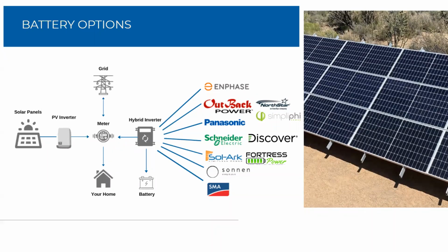So 4 kilowatt hours for a day means if I had a 12 kilowatt hour battery bank, that could get me easily through 3 days, 3 complete 24-hour periods. But if I have a 10 kilowatt hour day, my 10 kilowatt hour battery bank could potentially be drawn in 1 day. However, when I run my air conditioner, since I'm grid connected, I don't necessarily think about it. I'm grateful that I'm grid connected, and I turn my air conditioning on when my house gets too warm. If the AC is on, I could definitely easily be pushing 30 to 45 kilowatt hours in a day.